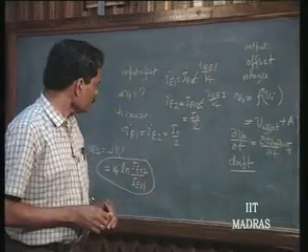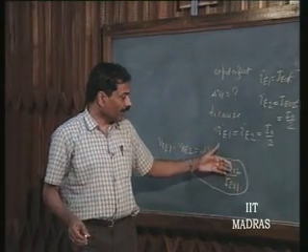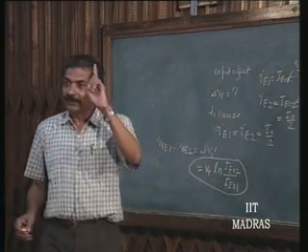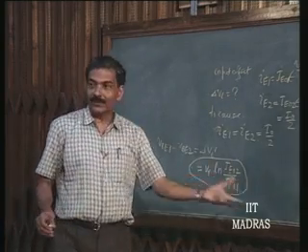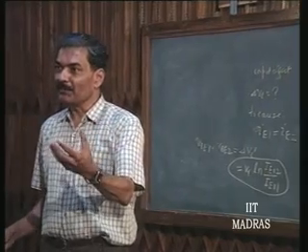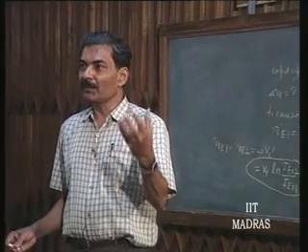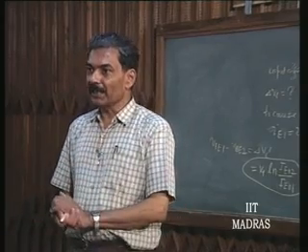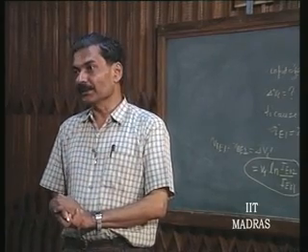So this is coming because IE naught 2 is not exactly equal to IE naught 1. This is very nearly equal to 1. That is why this logarithmic factor is going to be a small factor, and VT itself is 25 millivolts. So some factor of about 1/10 will come out of it, and therefore you get 1 to 2 millivolts as the natural uncertainty about this.